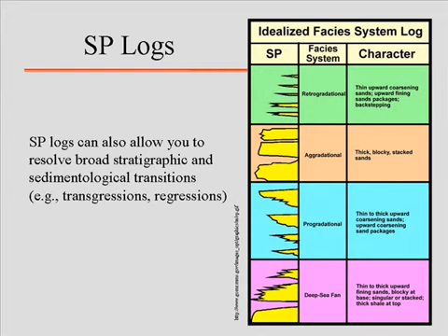And you have to remember, this is the key thing to note. If you're talking about sedimentation within a basin, you're fixed in terms of your spatial location. What's happening is things are shifting towards you as deposition changes. Sea level starts to drop, the delta is going to approach you very quickly. Sea level starts to rise, the delta is going to move back inland. So you're looking now potentially at sequences that are thousands of feet thick, that are representing hundreds of thousands, or in some cases millions of years of time.